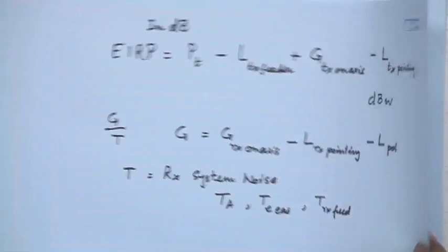Similarly, the noise power received by the satellite receiver also gets certain gain and comes down. So, at the receiver I see the quality in terms of the signal to noise ratio, carrier to noise ratio or carrier to noise power density ratio. How should it be related to the uplink carrier to noise ratio and the downlink carrier to noise ratio? There are two separate things. So, let us see how it looks.